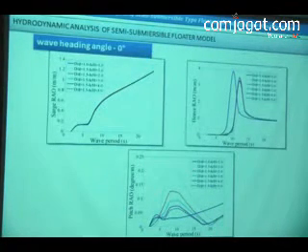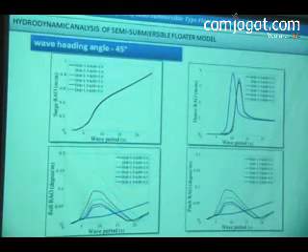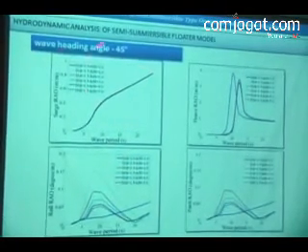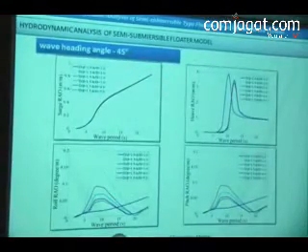These are the results pertaining to the surge RAO for the different types of semi-submersibles of different diameters and column heights, the heave RAOs and the pitch RAOs. From this, the floater with a ratio of 1.5 and H of 1 produces the least heave responses. And if you compare the pitch RAOs, all are relatively small. This is for a wave heading of 0 degrees. Then the same analysis was carried out for a wave heading of 45 degrees.